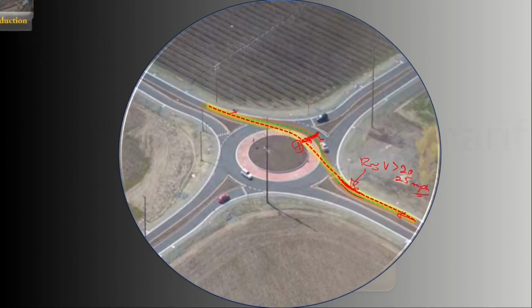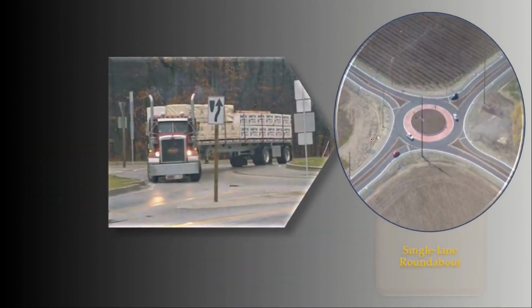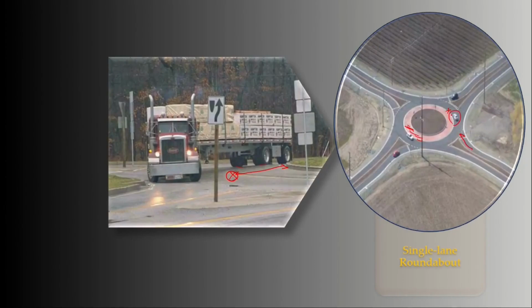But what happens to a larger vehicle making a left turn within the roundabout? This picture demonstrates how the roundabout handles it. The rear wheel path will climb over the transversable apron, while the edge of the apron dictates enough deflection to entering traffic, especially passenger cars.